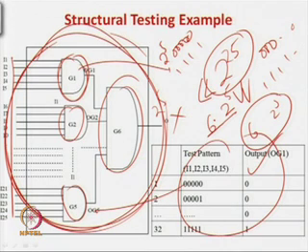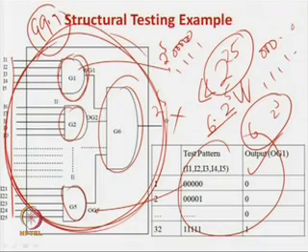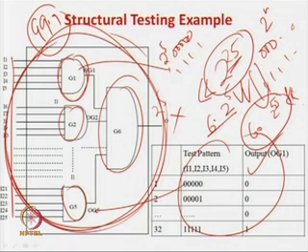But people have shown statistically that if you take this structural testing, the accuracy relative to functional testing is still as high as 99.9%. Now you have to understand one very important thing. What are we doing here? If you go for functional testing, you are applying 2 to the power 25 vectors. But if you are applying structural testing, then you are applying 6 into 2 to the power 5 test vectors. So, the number of vectors being applied is very small. You can call this 2 to the power n, and this is called k, as per our last discussion.